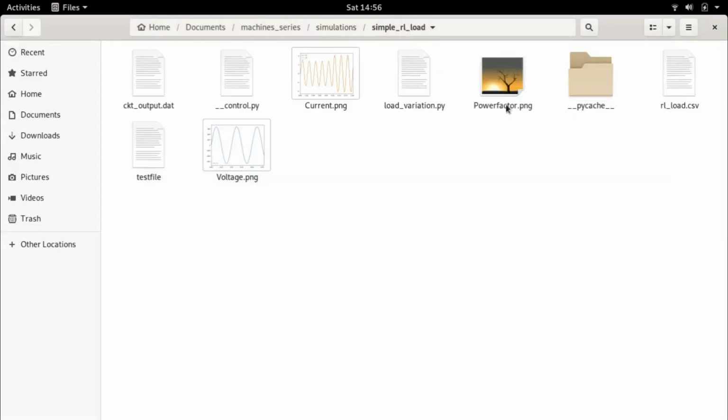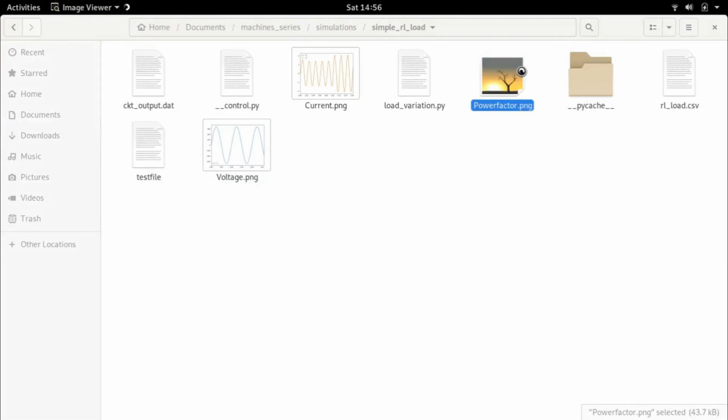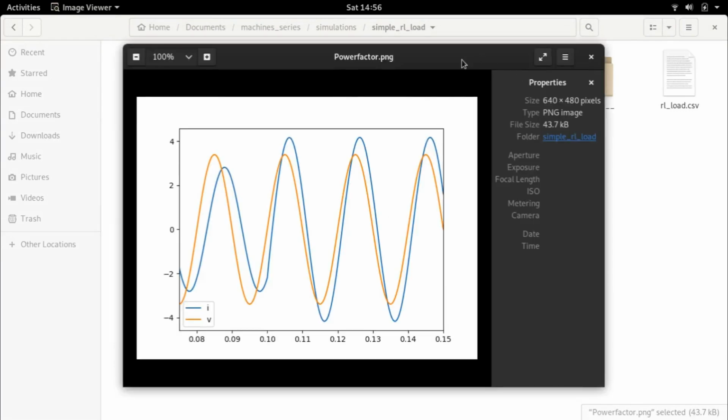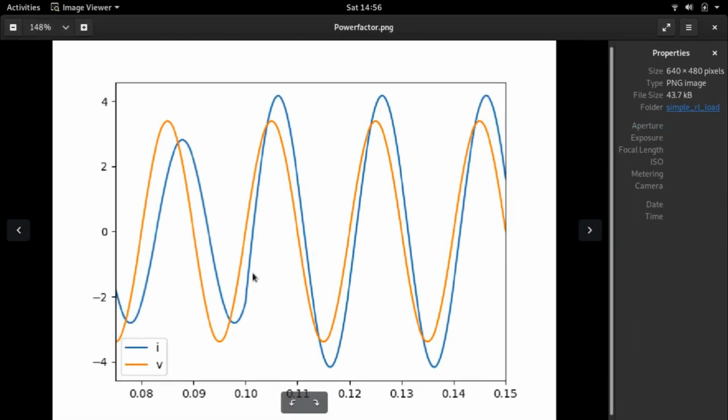And let's go back here. Have a look. Yes, it is now quite clear. So you see, the voltage remains pretty much the same because our feeder impedance is so negligible that even if the current changes by such a small amount, the voltage drop across the load does not change that much, right? Which is why it's pretty much steady. The current, however, has changed significantly.